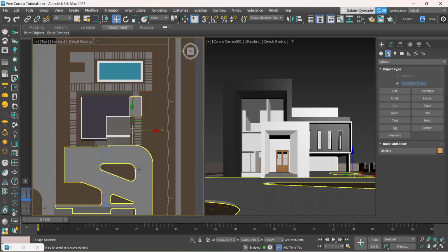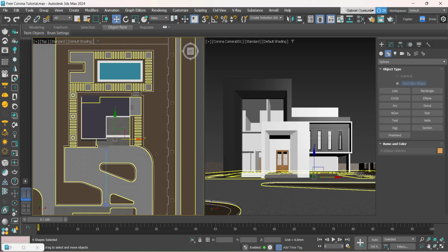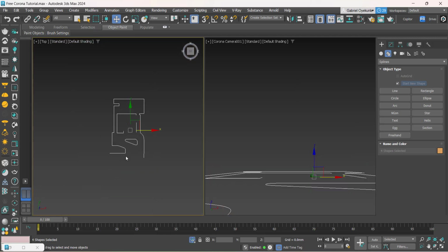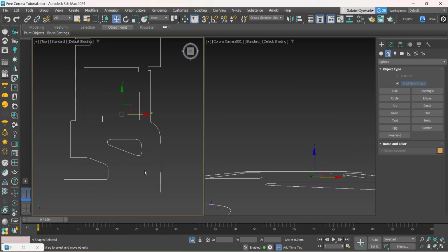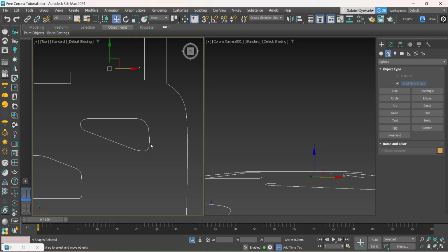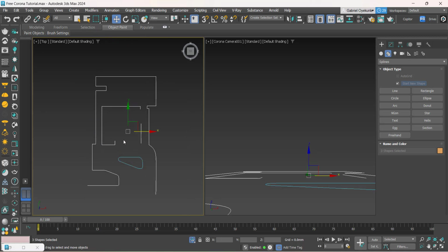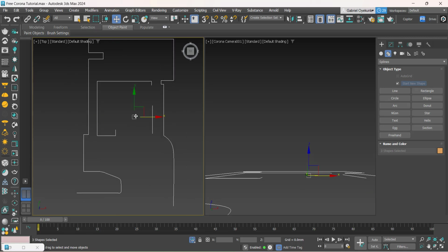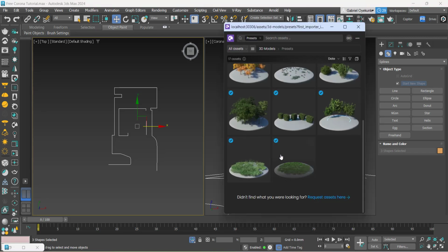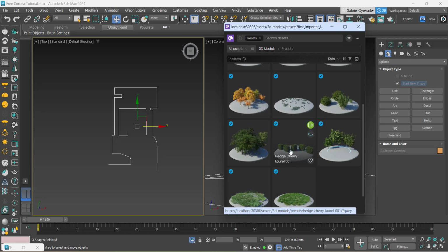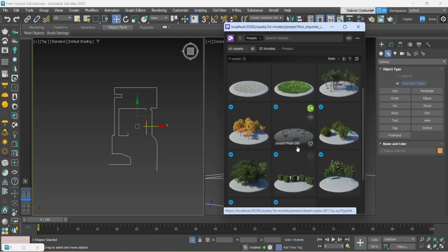and having done that, I can select all the lines and isolate them. The type of shrub I'm going to use here is different. So I'm going to press Alt and deselect it, then isolate again. Now I can come here, I see this laurel edges, and I think I like it.